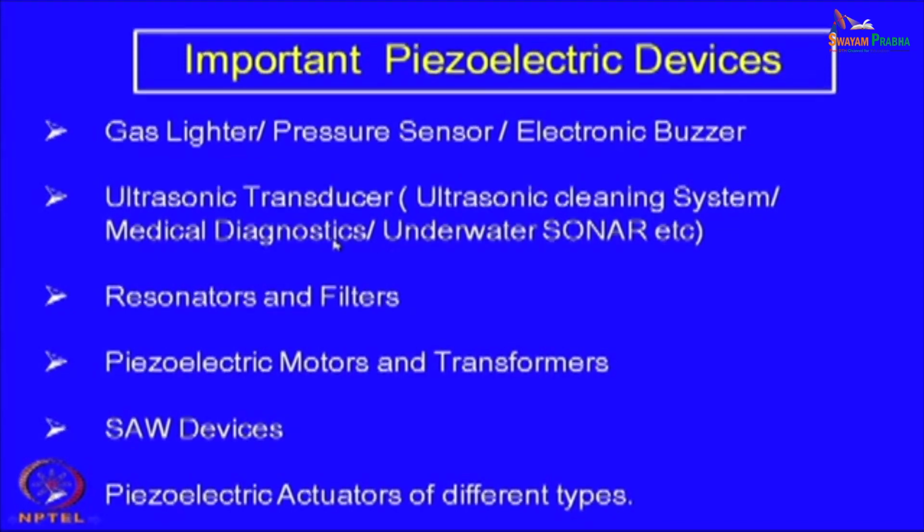If it is a solid medium, that is not a big issue, because the generator is also a kind of solid, and if it is a solid interface, the problem is less. If it is a solid-liquid interface, then the transmission becomes difficult, because at the interface you have what we call a big acoustic impedance.